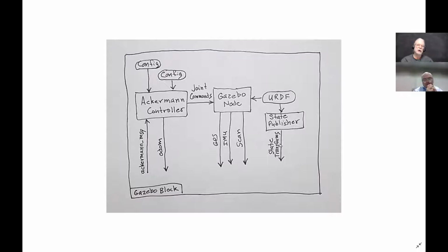So instead of going into a launch file saying create a static transform broadcaster, and I want to publish the difference between, say, GPS and BaseLink, and then give it all the numbers of what that is, instead, you can put that stuff in the URDF file, again, like Al is doing, and then start up robot state publisher, and it generates that stuff just out of that file. So that's two different ways to do that.